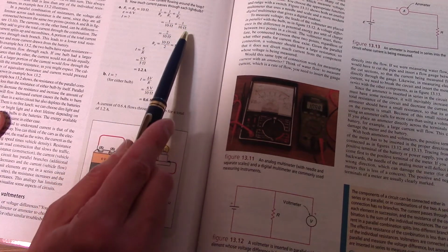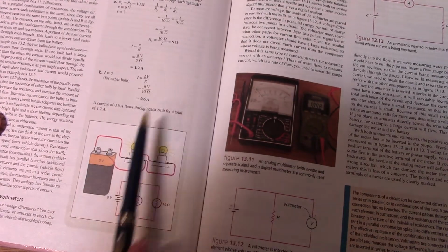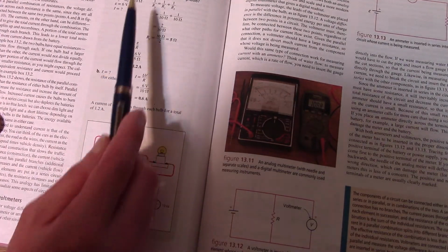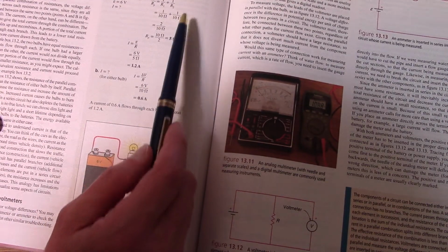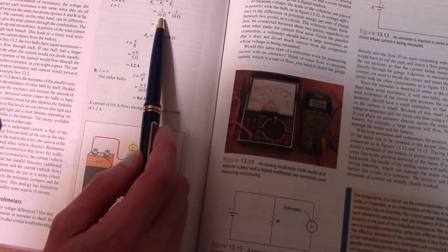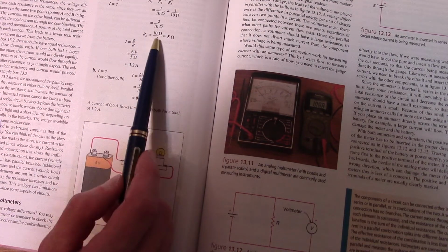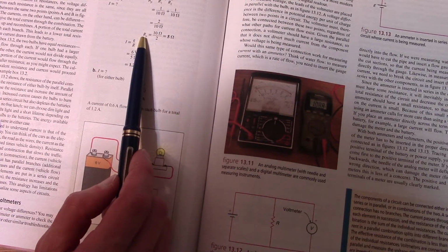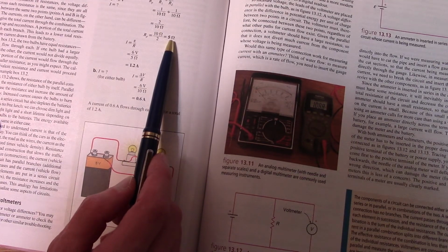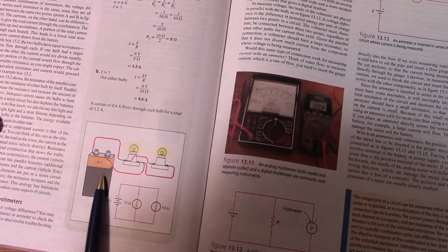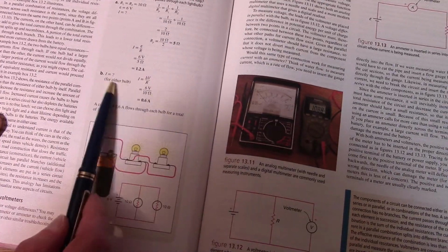Okay, and then it's our little formula. And then how do you get the final? Well, I'll go through it quickly. So they're saying that these resistances are 10 ohms apiece. So it's 1 over 10 plus 1 over 10. Well, 1 over 10 plus 1 over 10 is 2 over 10. But that's equal to 1 over your total. Well then, to get your resistance completely, you just do the inverse. 10 over 2 is 5. It's as simple as that. Then to figure out your current, you know it's a 6-volt battery. It tells you that. Divided by 5, 1.2. Okay? And make sure you do part B as well.